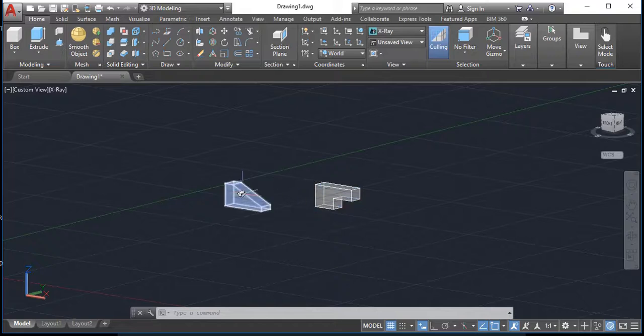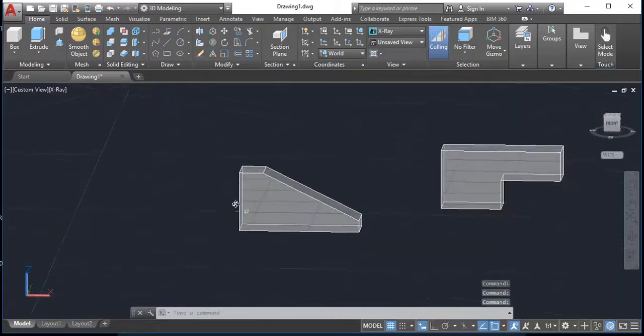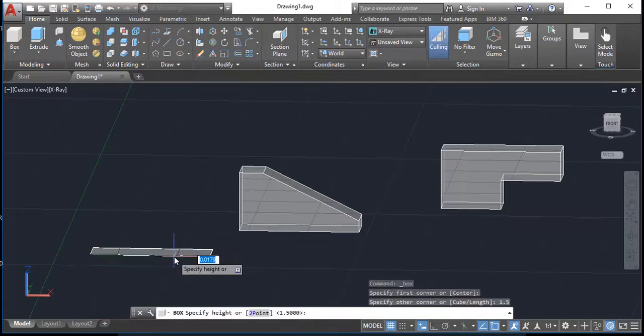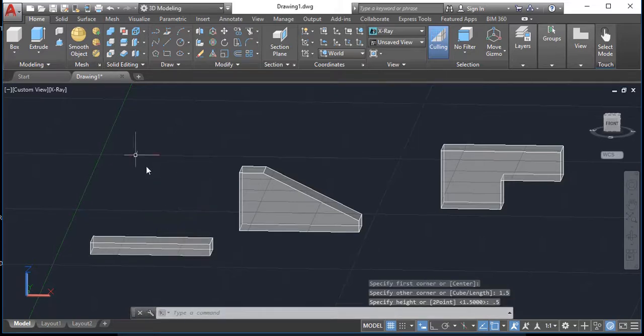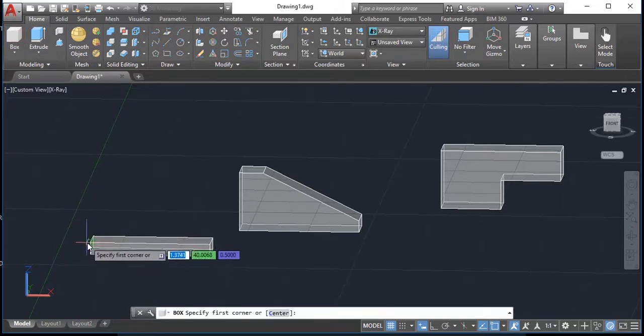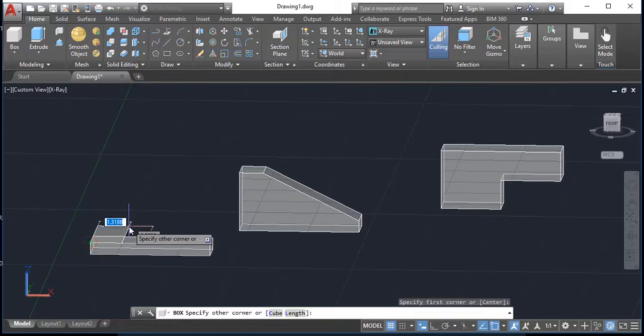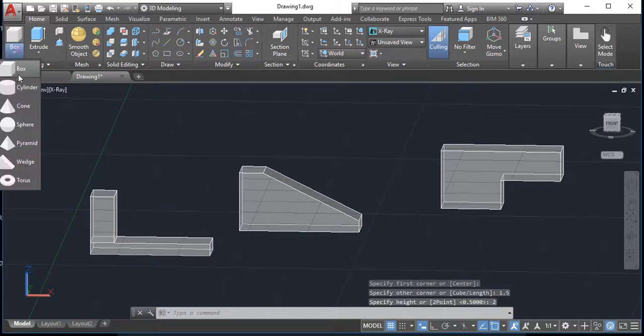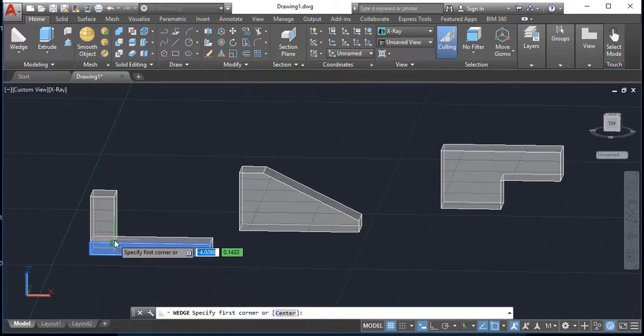Other shapes, you might have to join shapes. So let's say that for this one here, instead of doing a large rectangular box and then subtracting out the wedge, you could do it the other way. You could do, let's say, 5 by 1.5 inch deep by 1/2 inch tall. You could do that shape, plus a shape from this corner going out 1 by 1.5 by 2 inches tall. And then you could do another wedge shape here, snapping from this corner to this corner and snapping up this tall.